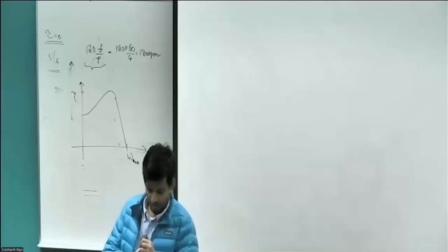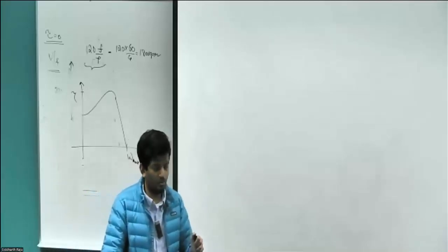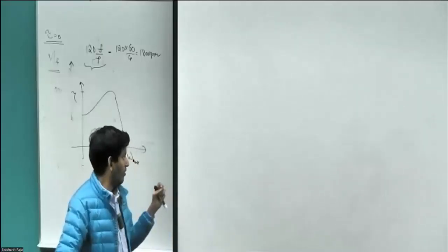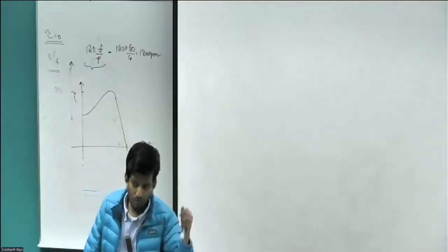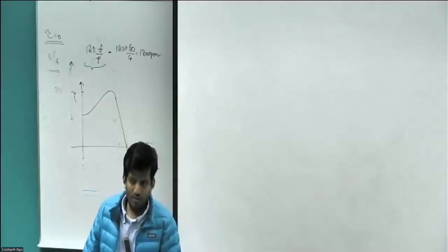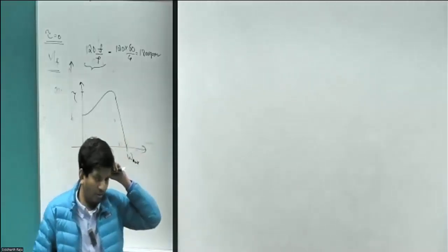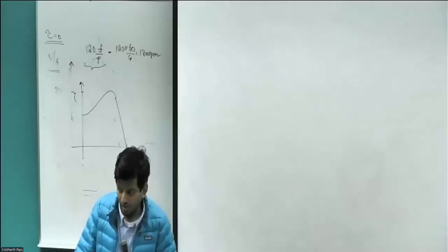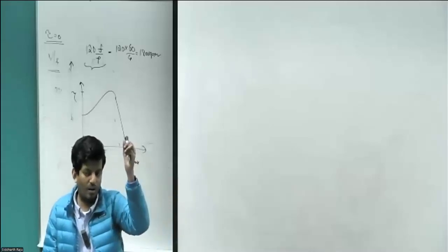So this is the biggest advantage of an induction motor compared to a permanent magnet synchronous motor, as we'll see in a minute. In an induction motor, there are two things. First, if you exceed the load torque and the motor comes to a stop, you can always reduce the load torque again. It will come back to operating at the same speed that it was operating at before it came to a halt. And the other biggest advantage is, as you saw, I directly started at the rated voltage and the rated frequency. I didn't increase the voltage to that value slowly.